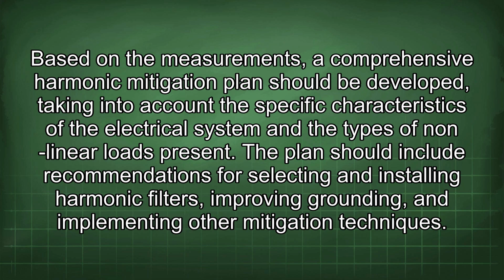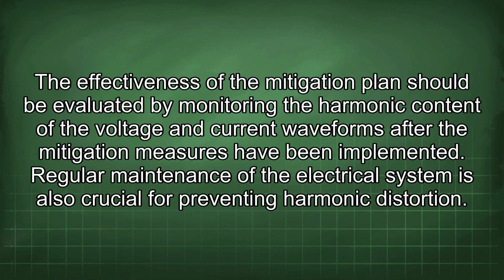The plan should include recommendations for selecting and installing harmonic filters, improving grounding, and implementing other mitigation techniques. The effectiveness of the mitigation plan should be evaluated by monitoring the harmonic content of the voltage and current waveforms after the mitigation measures have been implemented.